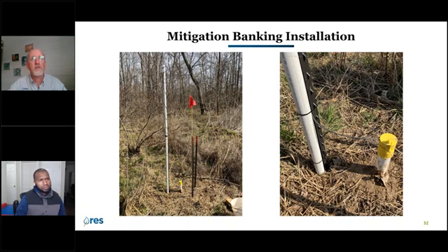If it's right after a rain event, it's going to absorb more. When it dries out, the radio signal can move through that canopy. As those trees get older and that canopy gets higher off the ground, transmission continues to improve. So think about your site. If you're in a mature forest where the canopy is well above your transmitter, that's pretty good. If you're in a really thick system, maybe one of the coastal systems with a very thick shrub layer, that's going to be more difficult, where you have water and all the leaves right in the same transmission area.